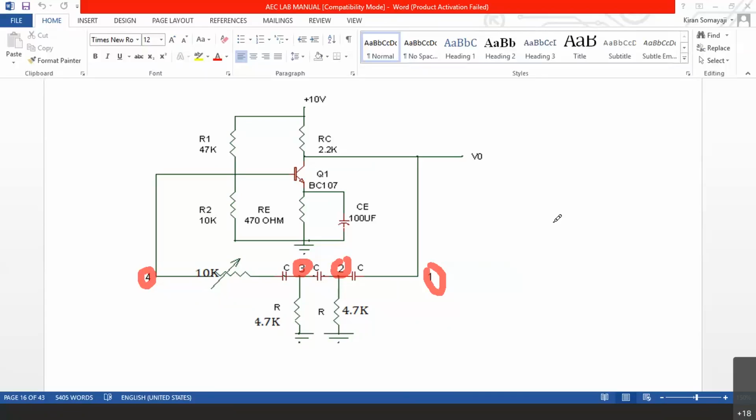That visible light is emitted from the phosphorescent screen, or so to say fluorescent screen, because of the hitting of the electron beam to the screen. Now that beam can be made to move up or move down, or made to move left to right by means of vertical deflection as well as horizontal deflection.